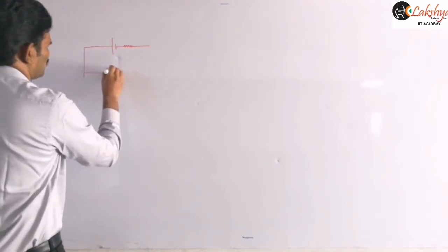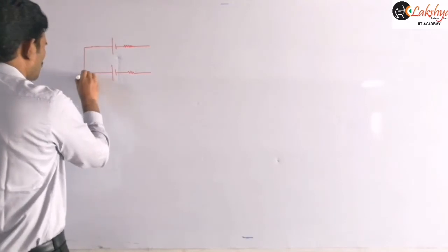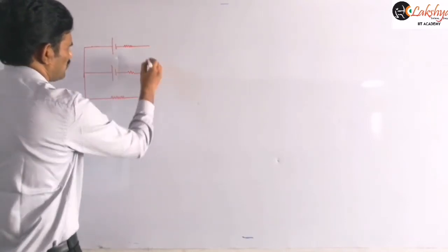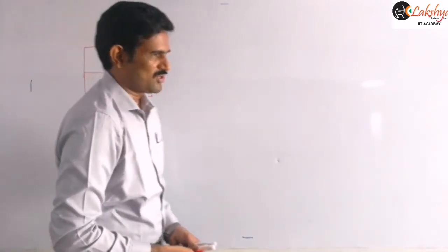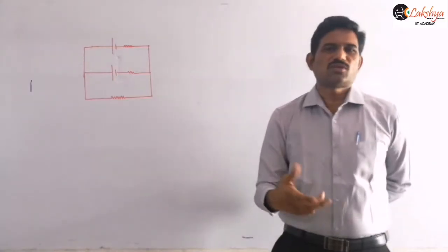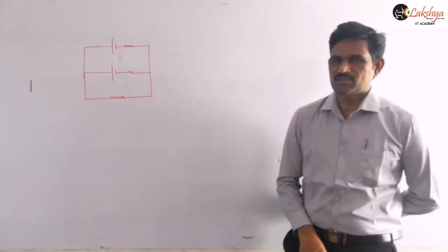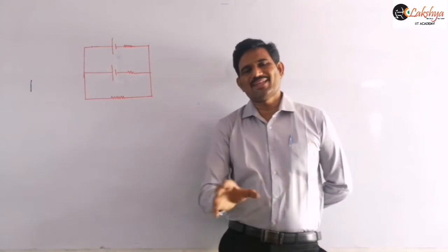So actually now while applying these Kirchhoff laws, first we need to assume the current direction here, because they won't give any current directions, as I mentioned, whether we are traveling in the direction of positive current or negative direction. In the circuit they won't give any current direction, so we need to assume the current directions there, right? And the advantage in Kirchhoff law is you can assume in any direction.